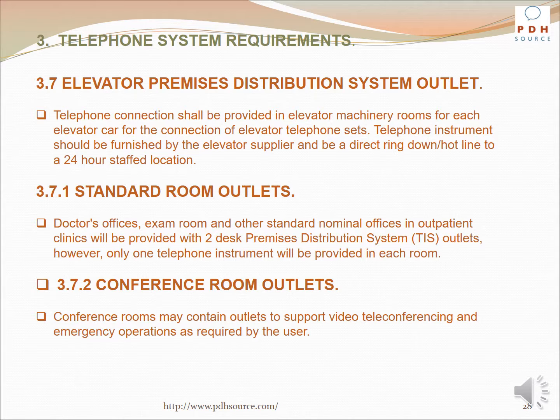Telephone connection for elevators shall be provided in elevator machinery rooms for each elevator car for the connection of elevator telephone sets. Telephone instruments should be furnished by the elevator supplier and be a direct ring-down hotline to a 24-hour staffed position. Doctors' offices, exam rooms, and other standard nominal offices in outpatient clinics will be provided with 2-desk premises distribution system, TIS, outlets. However, only one telephone instrument will be provided in each room. Conference rooms may contain outlets to support video teleconferencing and emergency operations as required by the user.